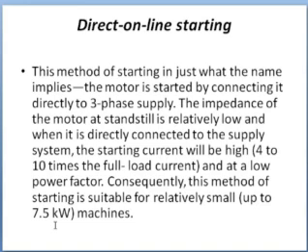If the rating of the motor is very high, then the starting current would be very high, and it will affect other consumers who are supplied from the same source. If high current is drawn from the supply, then the voltage may dip and it will affect the other consumers.